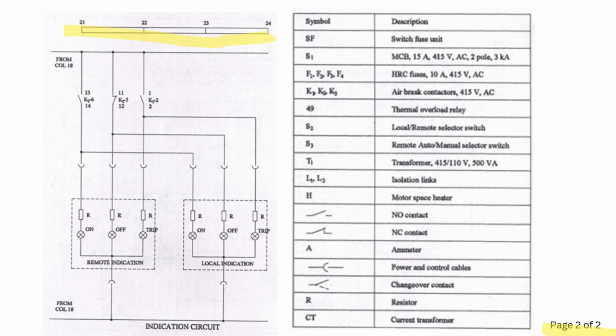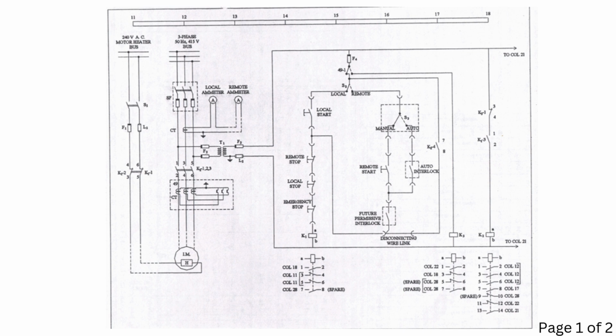When I say find the contactor in this diagram, it might be difficult for you to understand, and also there are so many contactors located in the diagram. Even if I say find contactor K1, it is still difficult to locate it. But if I say find contactor K1 in column 11, it becomes easy to identify the location of the device in the diagram.